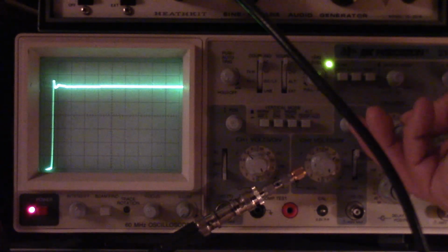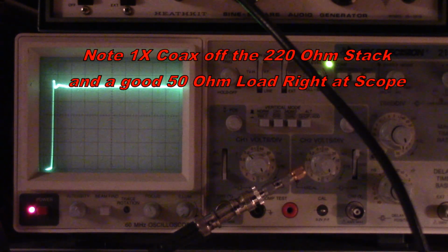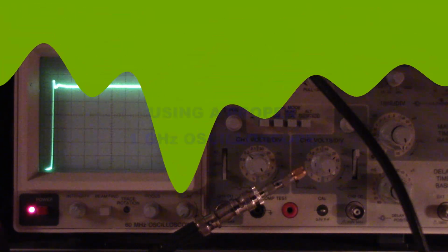So the next thing you should be asking is, Mike, how fast is it? I'm driving it with my little Heathkit sine wave oscillator, and I've only got it set for a modest 100 kilohertz. So let's see if we can get the rising edge. I have my scope set as fast as it will go, which I believe is 50 nanoseconds per division. That's probably beyond the capability of this very modest oscilloscope. It's only a 60 megahertz scope, so we are being limited by the scope.